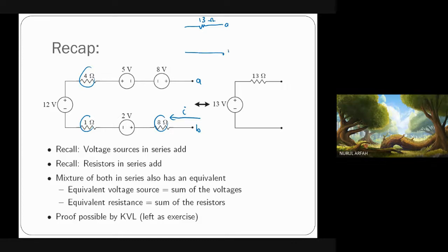After that, look at the current direction. It is going to the left. And then you find 2 volt. 2 volt. And because the current enters the positive first, then you should put a positive, right? Positive 2. And then the current goes to the next voltage source, which is 12. You have a negative, right? Negative 12. And then this one, is it a plus or minus?